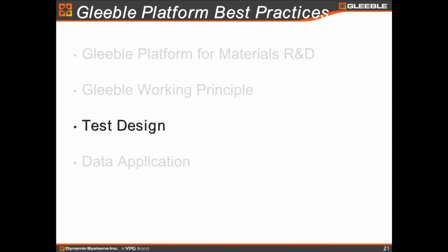For example, Dr. Suzuki at Nippon Steel, when he used the Gleeble to do the castability map, asked his people to do 3 tests for each point, because with 3 tests, if one of the tests is really off, you can just throw it out, or take the average to make your test data much more solid.